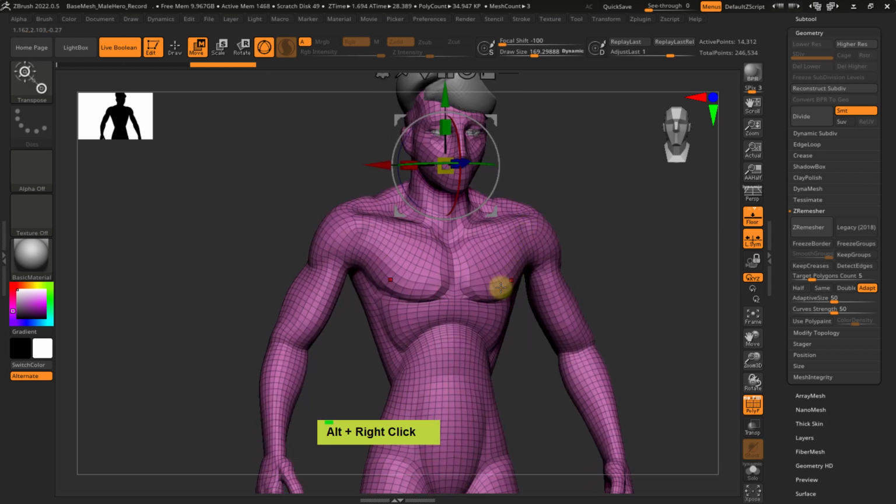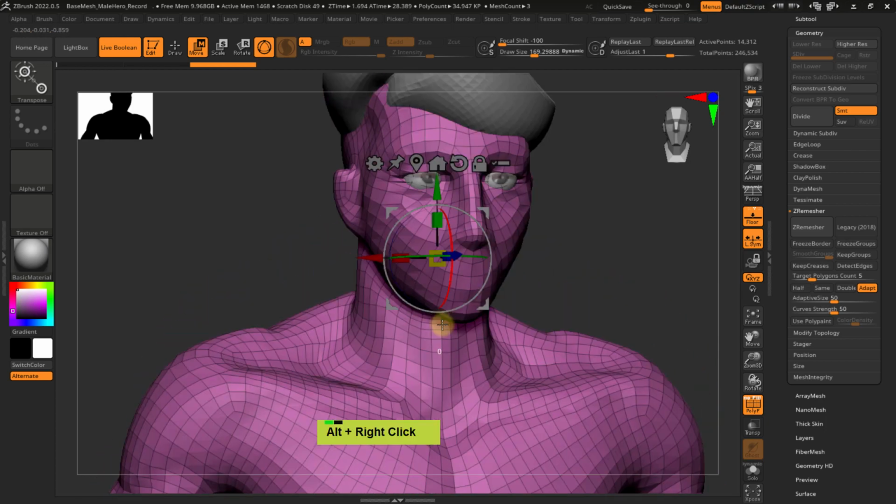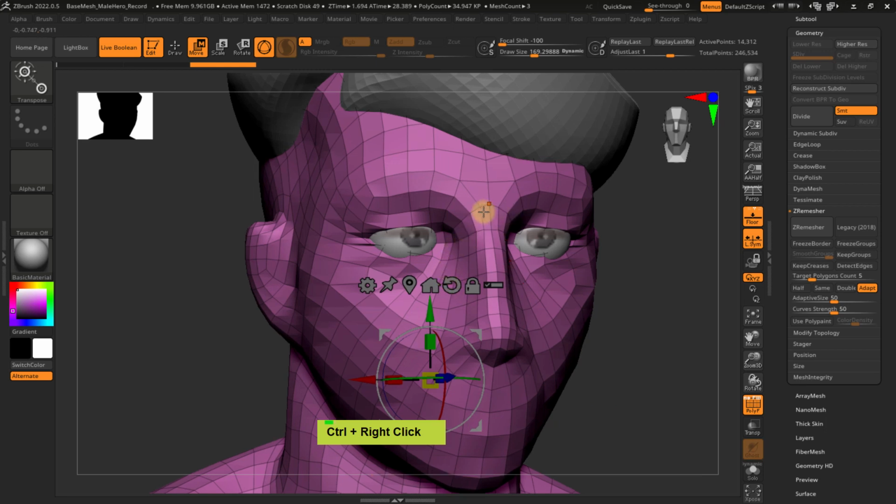First of all, the reason we want to alter things is because it's a sculpting remesh. What does it mean? For sculpting, the resolution is pretty important. So with the ZRemesher, these settings are trying to maintain a somewhat uniform polygon size.